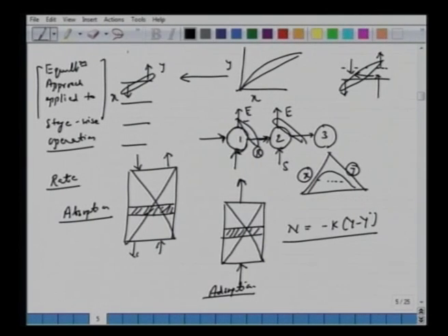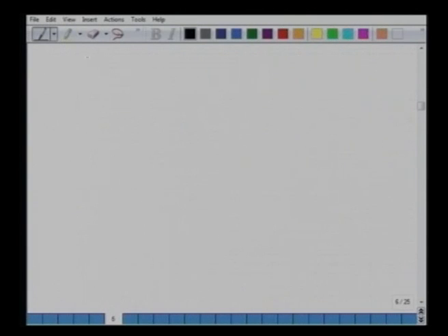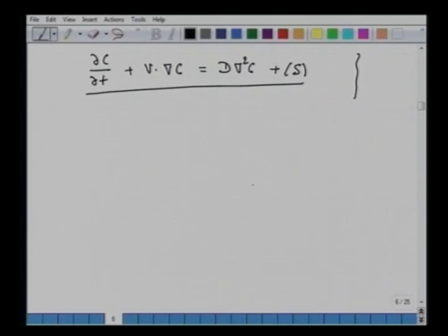Here, since the process is continuous, we have the rate-wise approach, in which case we wrote down a very comprehensive species balance of this order. Species is brought in and out by convection, species is brought in and out by dispersion or by diffusion, and then we have the rate at which mass is transferred from one phase to another phase. Then in principle this has to be solved with certain initial conditions and certain boundary conditions.